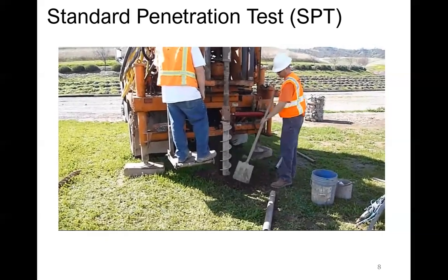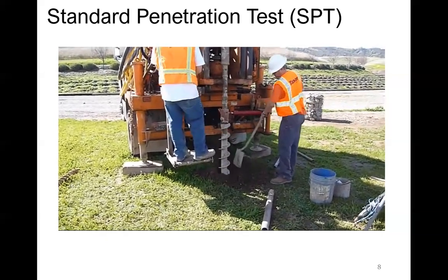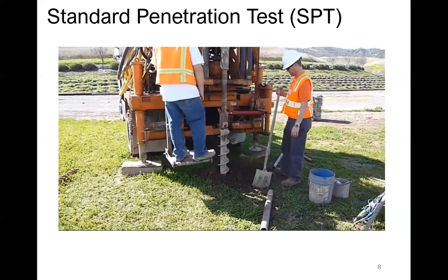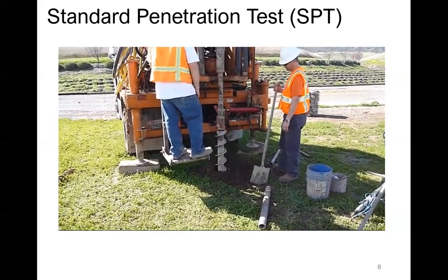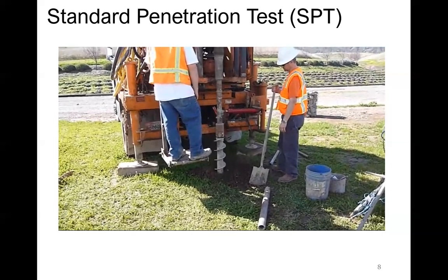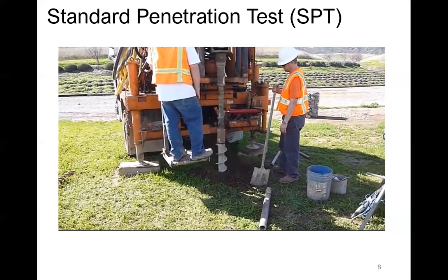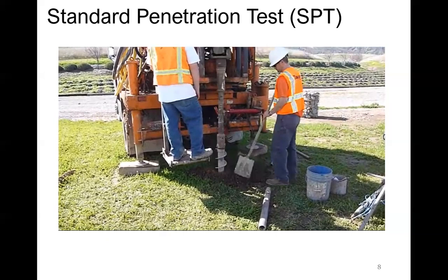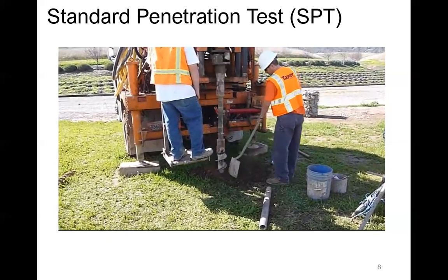So what he's doing, they're augering right now. So that's the continuous flight auger. That auger on the outside is pulling all the soil up, even though you can't really see. It's starting to have a little mound on the base of it. So they're going down to their required depth.